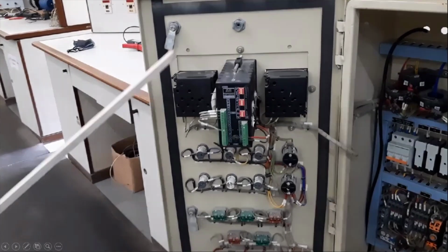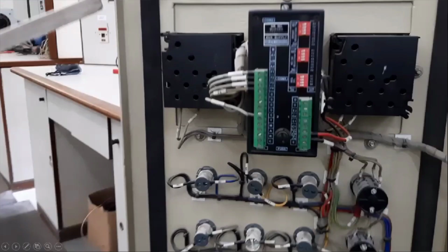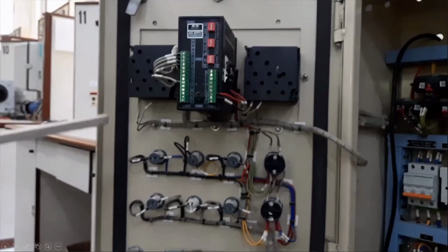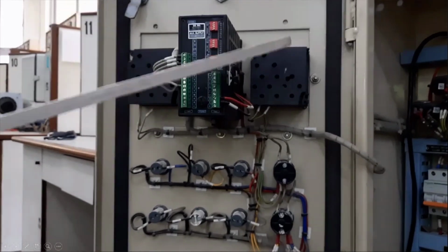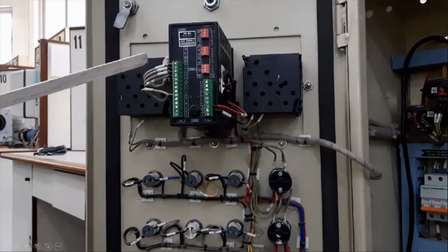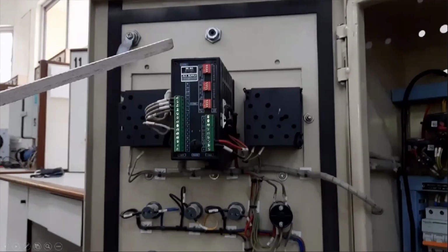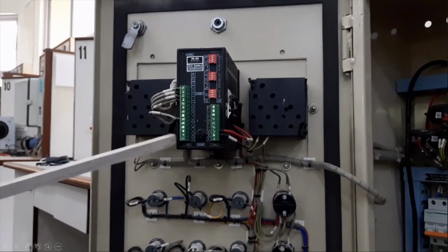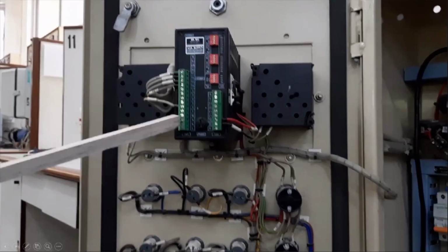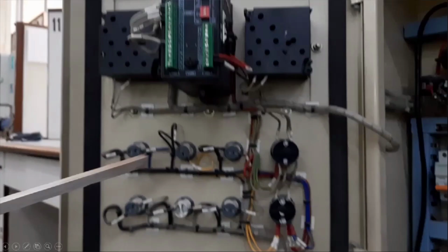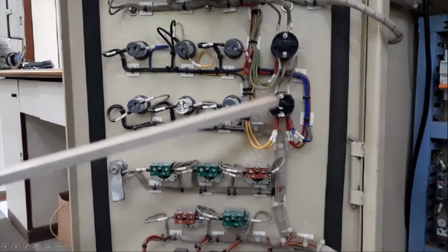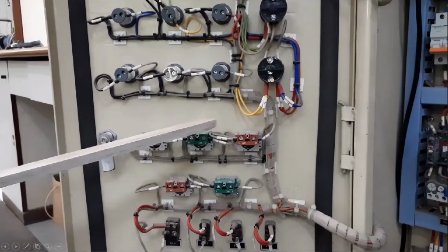Okay, so right now we have opened the panel, and now you see this is the back view of the front door what we have just seen. These are the back views of the voltmeter and ammeter. This is the back view of the microprocessor based annunciator. Depending on the settings on this switch we can configure the various faults, and these are the points where you can give the information to the annunciator that a particular type of fault has occurred. These are the LED indicating lamps. These are the selector switches, and the backside connections are there. These are the start stop push buttons, and these are the toggle switches.